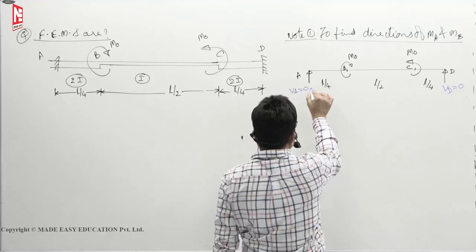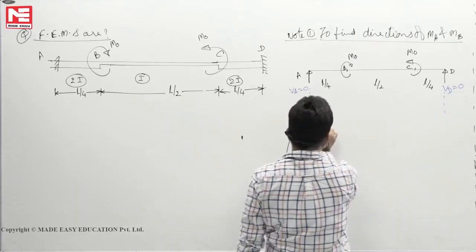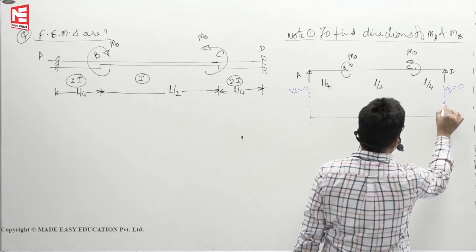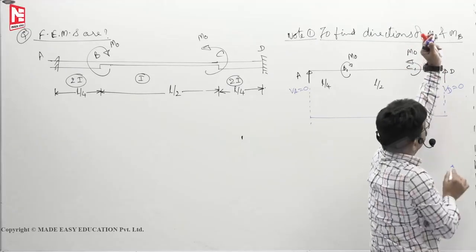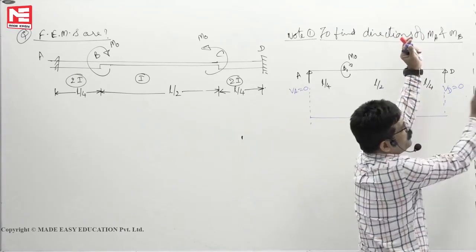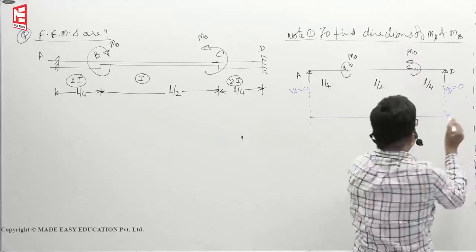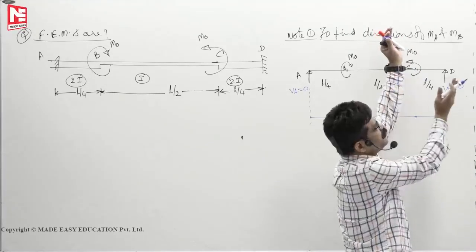Now when you draw the bending moment diagram for this one, it will go something like this. Between D and C, bending moment is 0. Move your finger up to the right hand side of C, stand there, look right side. No load, so bending moment is 0. Now at LHS of C, stand here, look right side.